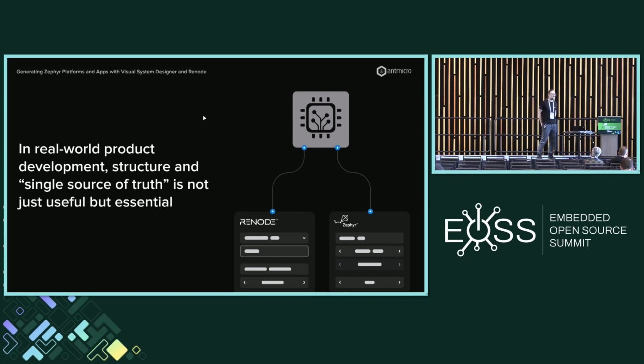Instead, we rely a lot on automation and the data being correct. So we just have to find ways to work differently. We have to find ways which don't involve engineers spending time on tweaking little things here and there. It has to be scalable. So we use the device tree as a common data model, and that feeds both Zephyr and Renode, and we make sure that those are correct, because both our Zephyr work and our Renode work needs this.